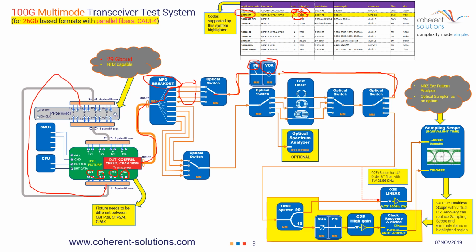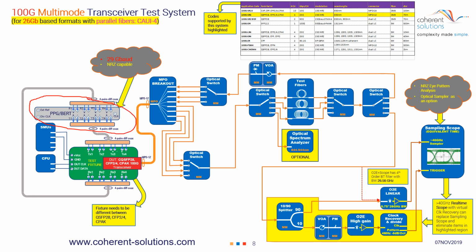The purpose of the bit error rate tester is, of course, to measure the error rate. Normally, when there is no attenuation and the transmit signal only has a few dB, you will have error-free operation, as indicated by the error rate that this bit error rate tester is measuring. However, remember, we have a VOA in series with this optical path that is returning the transmit signal to the receive side. By increasing the optical attenuation, we can keep attenuating the signal until such time the bit error rate tester starts noticing when errors occur.